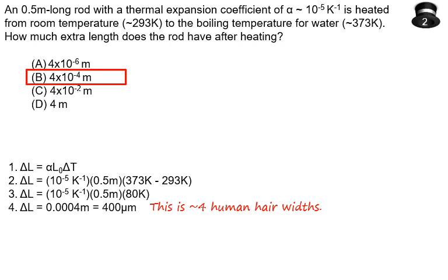If you had the same change in temperature and the same linear coefficient of expansion, and instead you had a 500 meter long rod, that's 1,000 times larger, well, that's a 0.4 meter or 40 centimeter change in length. So that is now appreciable, right?